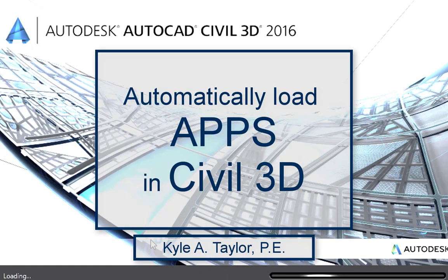A couple other things I would note, guys, is for method one, your support file paths will obviously look a little bit different. I just recommend finding one that ends with support, because that's where the rest of your AutoCAD fonts and all that kind of stuff already are anyway. Make sure it's a directory that you have access to. You should have a support folder almost identical to the one that I chose if you're running on Windows.